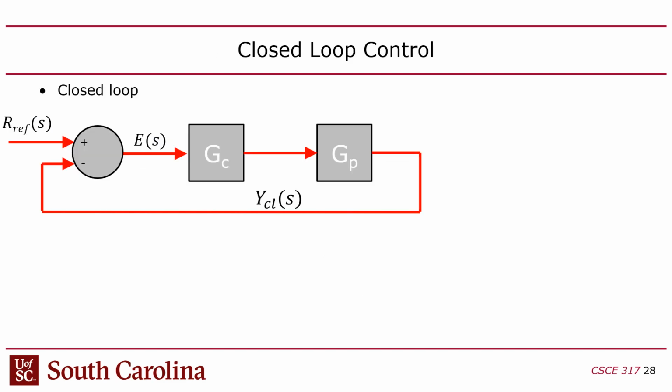Okay, so that's transfer functions. So how about the controller? How do you build a controller? We talked about closed loop control, and we talked about how you can combine transfer functions, you can convolve them, you can merge them together. So if you have a plant, this is the plant transfer function, and I'm going to create a controller transfer function, right? And I'm basically going to feed the controller into the plant, okay?